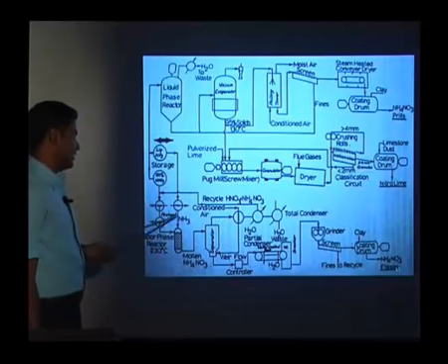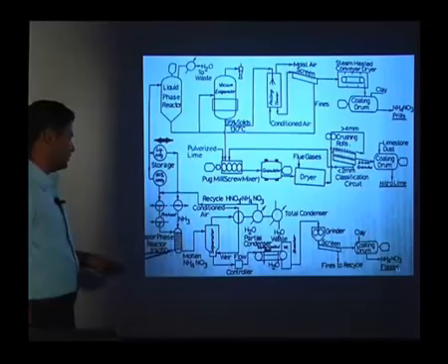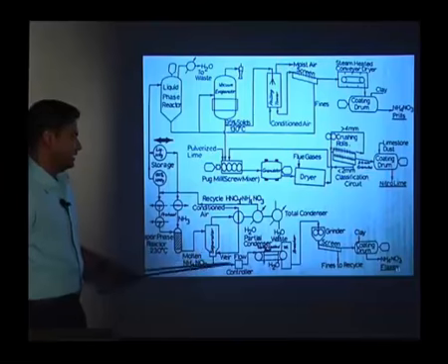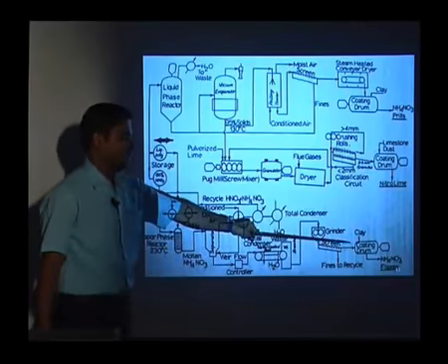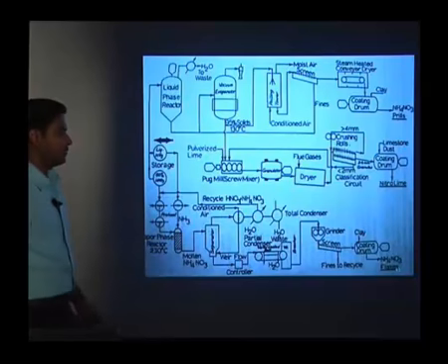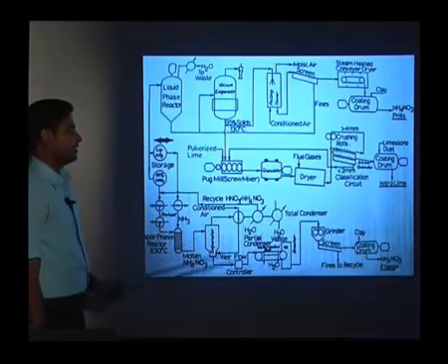Or we can have the molten NH4NO3 over here, and from the vapor phase reactor at 230 degrees Celsius, it is separated and then ground, and the flakes which are formed are coated, and we can have the final product as ammonium nitrate flakes.